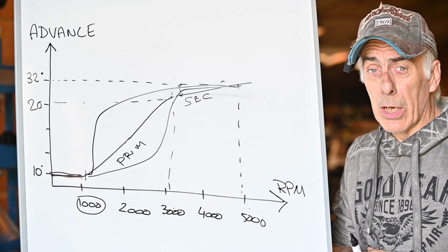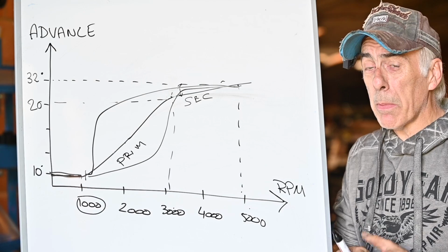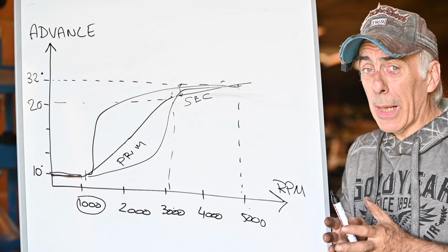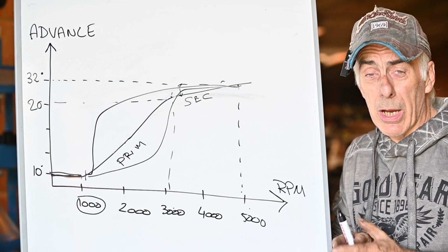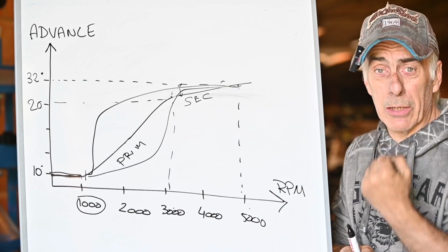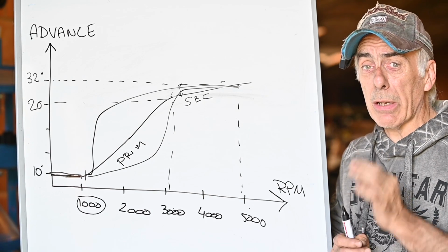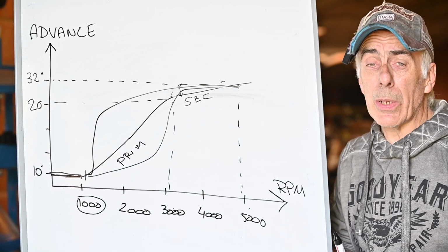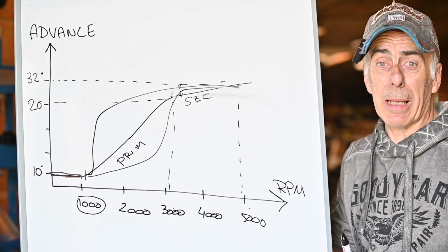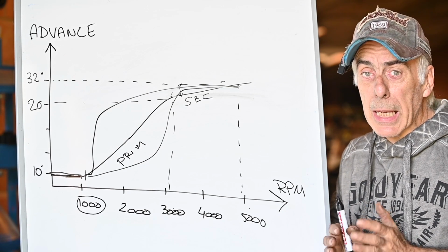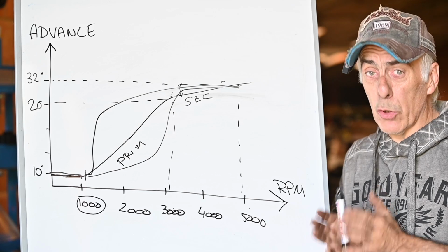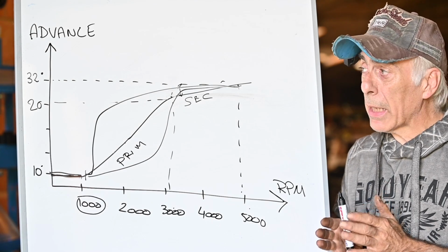In other words, you're going to have ignition and the maximum explosion part will happen prior to top dead center, and you're going to start pushing back that piston in the wrong direction where it's coming from, and you don't want that. And you can hear that very well on your car. Once you're going uphill and then you floor the pedal, you will hear that pinging sound. That means you have way too much advance, and you have to work on that and reduce it.